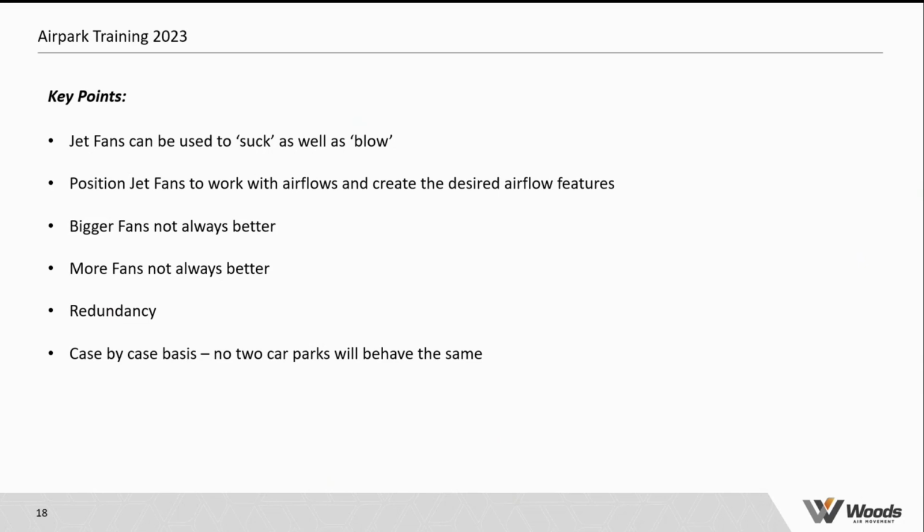And if your mass flow through your system is greater than what the extracts are capable of extracting, you're going to create a certain excess mass flow, which will not be able to be extracted by the extract fans, which will then have to be recirculated back around into the car park, meaning that the car park will retain some pollution and some contaminants within it, despite the system operating as intended.